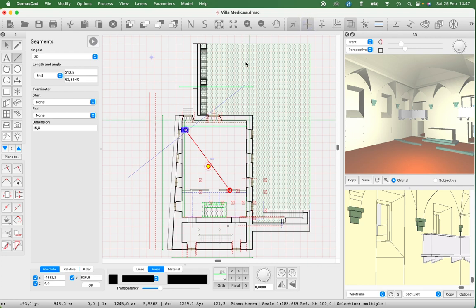The next icon shows or not the Cartesian axes, drawn in green, and the origin. Then place global origin and local origin. Show all layers or only the current layer. Show mouse axes allows you to see two axes at the mouse position, tilted like the angle of the drawing board, useful for finding alignments.